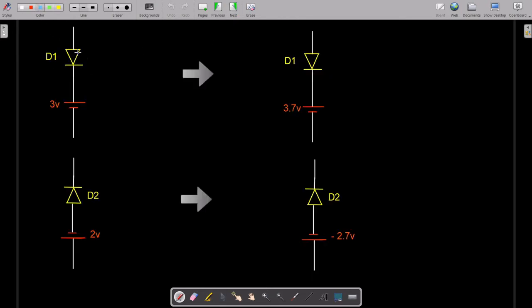Since our diode is a silicon diode, obviously the depletion layer voltage, that means VD, would be plus minus 0.7 volts, and here it would be minus plus, because here the N type is connected above and the P type is connected below. Minus plus 0.7 volts, correct.